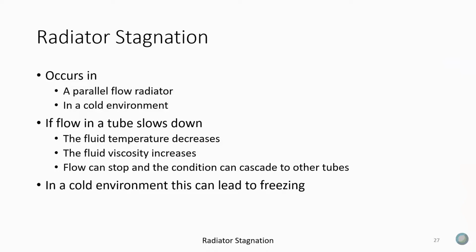So the idea was that we'd let the flow slow down in some tubes as we were in a really cold environment or to lower heat load. And then we come back and we get to a warmer environment, flow will go back in naturally. And when you read the reports, they had a bear of a time getting this thing to work. The idea was that you had different manifold lengths to vary the flow through each of the tubes. They were in the chamber cutting and fitting with tube lengths, trying to do it by modeling.